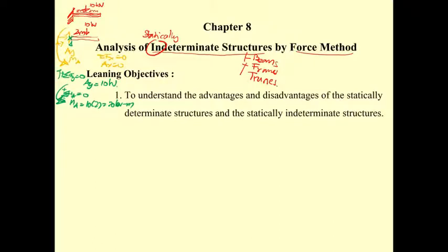Okay, and you can draw the shear diagram, the moment diagram, and you can also draft the elastic curve of this beam. Since this beam is fixed on only one side and free on the other end, this beam may have very large deformation. You can use your ruler and push the force at the middle of the ruler. You can see this part of the beam is going to curve, and this part of the beam is a straight line.